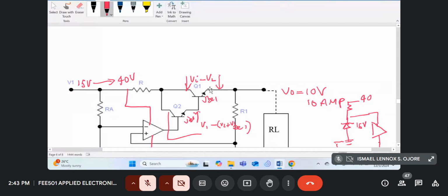So even though the transistor is completely on, approximately 0.2 volts would be lost across this transistor. And that's what we mean. So apart from its minimum operating voltage, you got to ensure that your design voltage plus 0.2 volts across this transistor must equal the minimum power supply voltage.